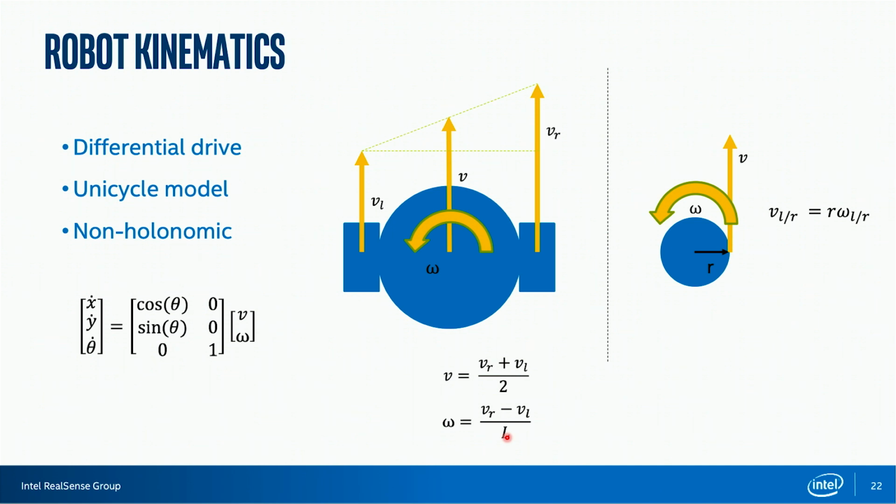Despite the simple kinematic model, it only has 3 states moving in the plane and 2 inputs, yet it's a nonlinear model and non-holonomic, meaning to steer the robot to a desired target configuration, one basically has to solve the parking problem, or simply speaking, the robot cannot move sidewards. And I will talk a bit more about the control on one of the next slides.